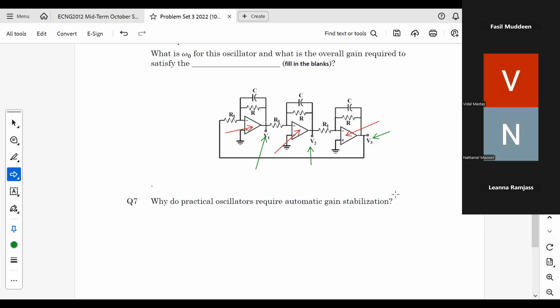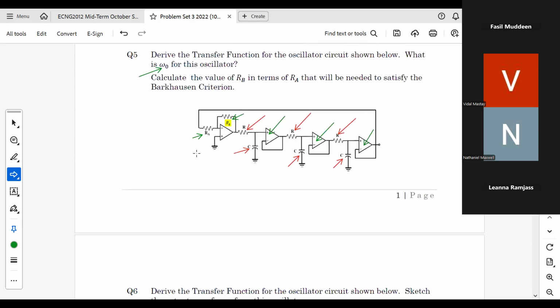Right, the one that used the thermistor, the other one that used a little feedback power supply that produces a negative voltage through a field effect transistor, and then the last one that I showed you, for the Wien bridge, was to use a pair of Zener diodes on the output. What that does is that as the output starts to get close to saturation, the Zener diodes start to kick in and bypass the output resistance and convert the waveform into a sinusoid. It prevents it from going past whatever the voltage is on the particular Zener diodes. All right. So all of these answers are in the notes.